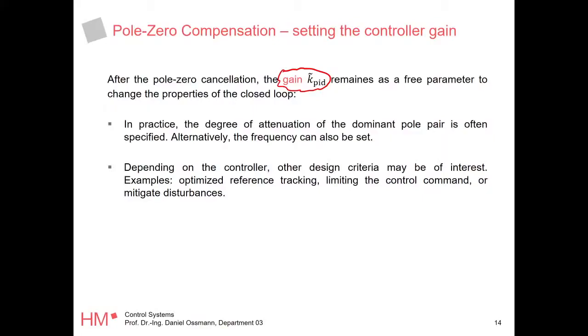But in practice, if you're ever going to go into controls and look back to that lecture, you need to be aware of the fact that you can use this gain. It's another free parameter for what you like. You can speed up your system even further. You can shoot for an optimal damping, 0.7. You can set a frequency. You have one free parameter, so you can tackle one additional design requirement.